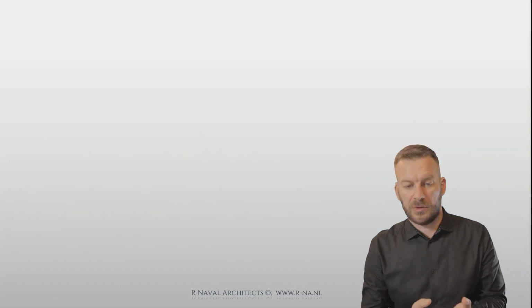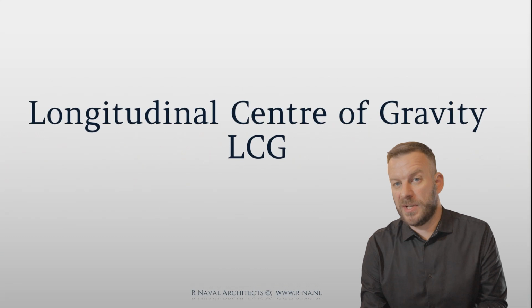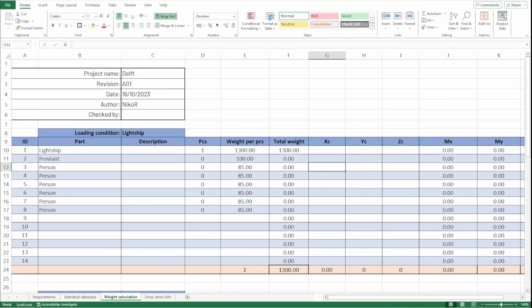This means that we need to calculate the longitudinal center of gravity for our boat. And then we will check how it will float with that value. So let's open our spreadsheet again and start filling in the positions of the mass, of the weight. And you can see for people it's very easy. We know where the seats are, so you just measure and that's about it.